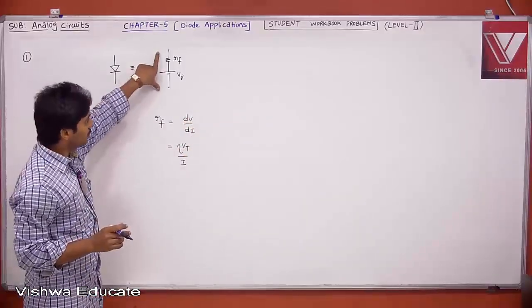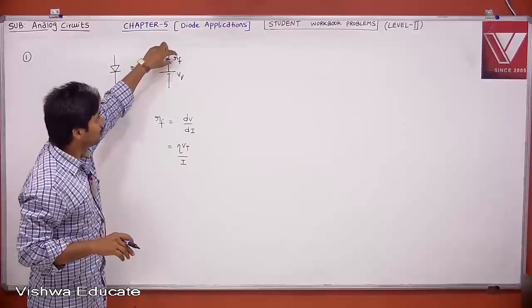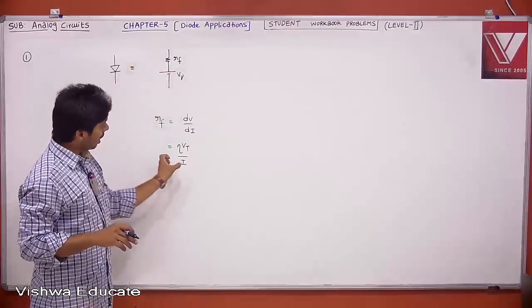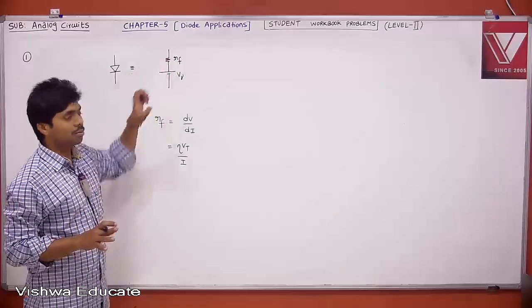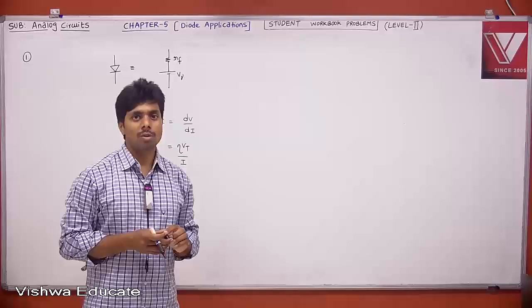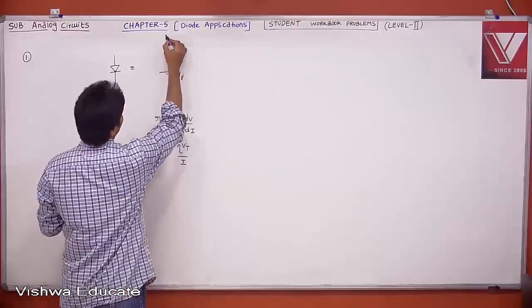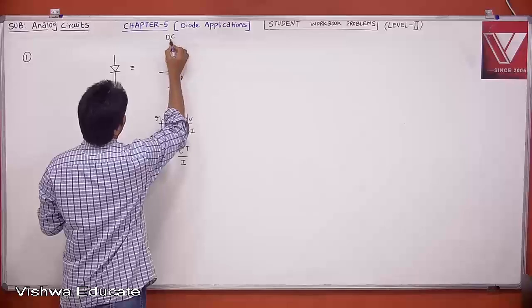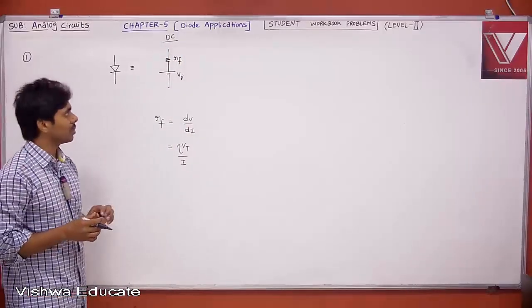If this is the third approximation model and you take RF constant, then it is the third approximation. But if you take this RF with respect to your bias current, which is from the accurate model, then this model is almost matching your exact model. But remember, this is for DC operation, for DC voltage or DC signal excitations.